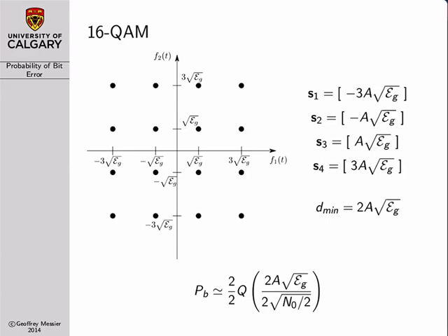So if you take a look at this signal constellation, basically you can make a square constellation by choosing one of 4 values on the x-axis and one of 4 values on the y-axis. And so really, square QAM is equivalent to 4-ary PAM, where you've got one PAM modulator working along the first basis function along your x-axis, and one PAM modulator working along the y-axis.